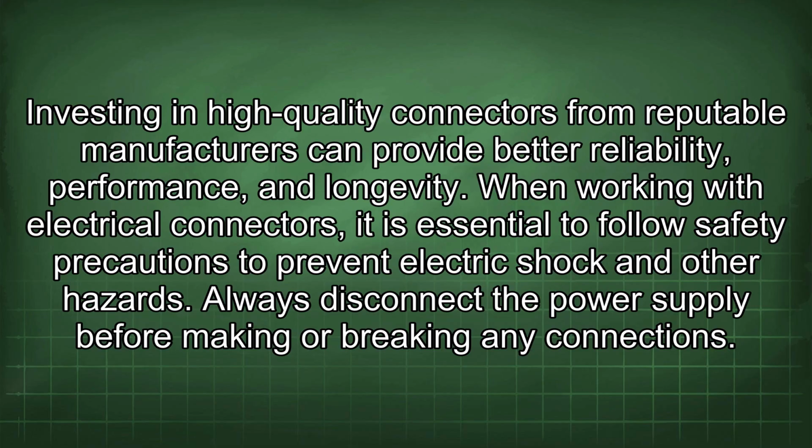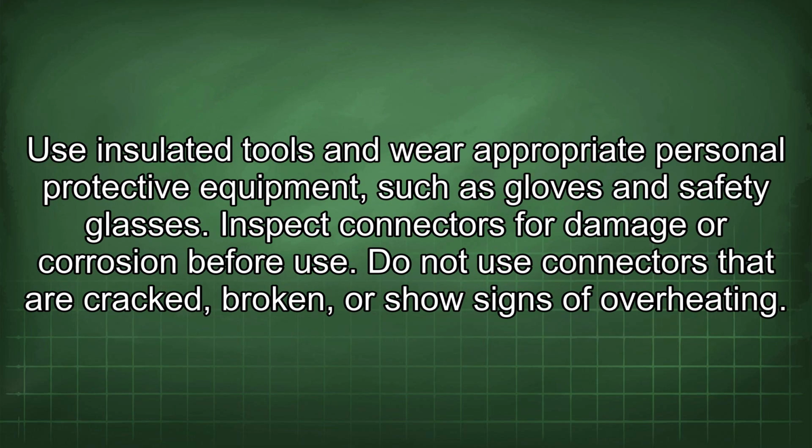When working with electrical connectors, it is essential to follow safety precautions to prevent electric shock and other hazards. Always disconnect the power supply before making or breaking any connections. Use insulated tools and wear appropriate personal protective equipment, such as gloves and safety glasses. Inspect connectors for damage or corrosion before use. Do not use connectors that are cracked, broken, or show signs of overheating.